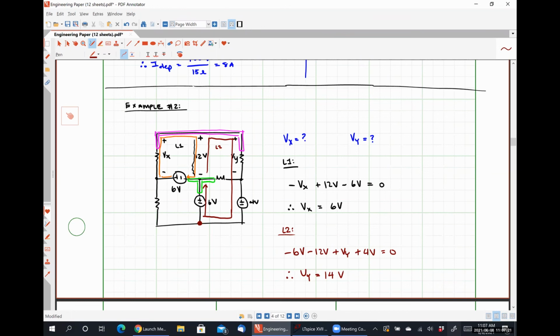So that original gray path that we took, we could have actually used by assigning another variable voltage to that particular resistor and then using another KVL loop to figure out what that voltage is and then substituting it back in. But again, that's not the quickest or most efficient path, so that's why I discouraged us doing it.